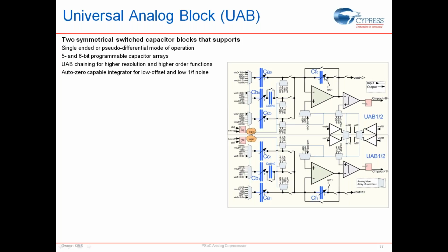Now think of the case where instead of having your feedback capacitor be a switching capacitor, you make it a non-switching, continuous time capacitor. What you effectively have done is created an integrator circuit. So the input side is switching, bringing in quanta of charges, and you're throwing that out into the feedback capacitor, which acts like a filter or an integrator that keeps integrating these small error voltages that are coming in from the input capacitor. So you could build integrators using this.